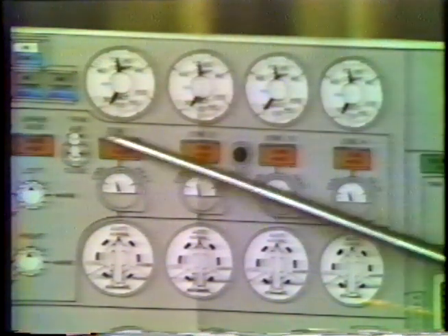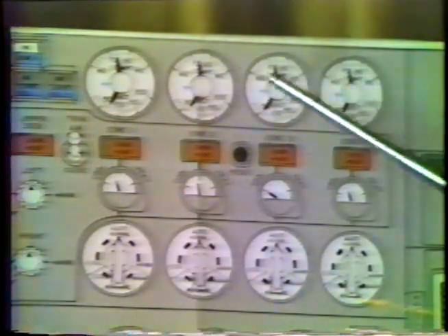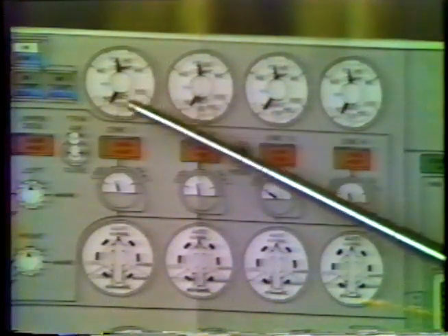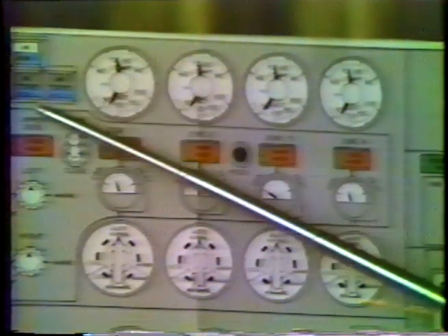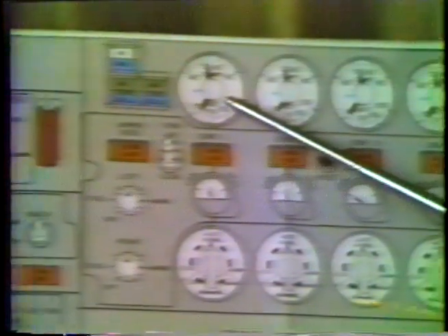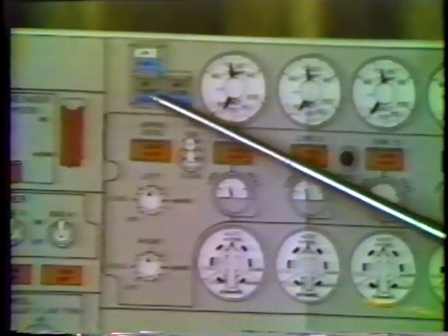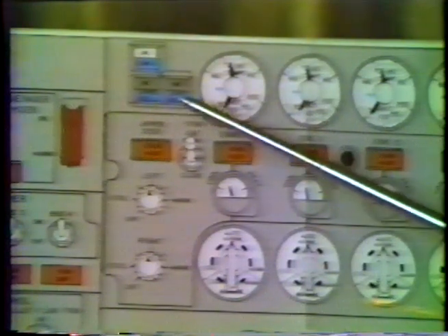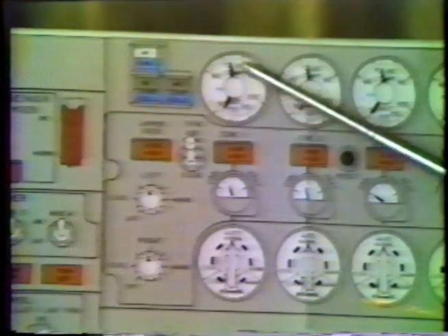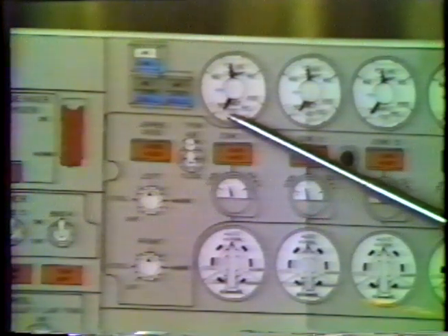The Zone 1 duct supply temperature indicator is unique in that you can look at the upper deck in addition to looking at Zone 1 with this series of push buttons here. The upper button connects it to Zone 1, which is the cockpit, and then below it we have two push buttons, upper deck left and upper deck right, which change this gauge from the cockpit to monitor the compartment temperature and the duct supply temperature in the upper deck area.